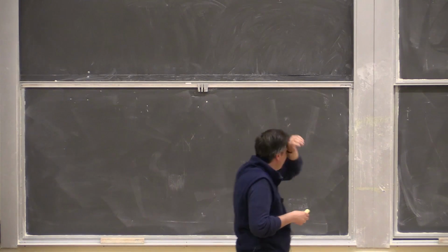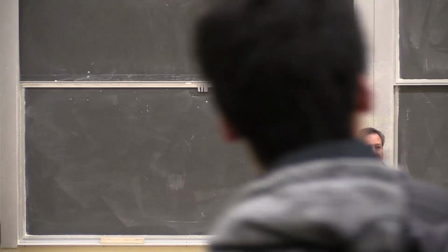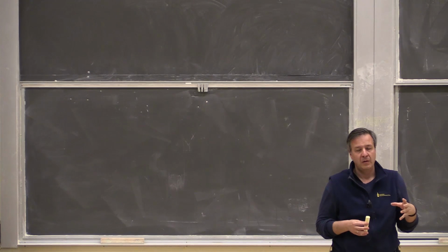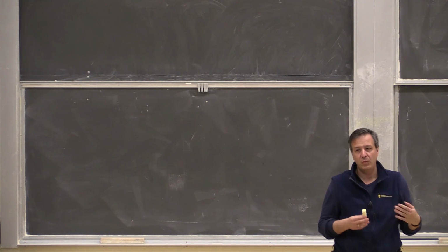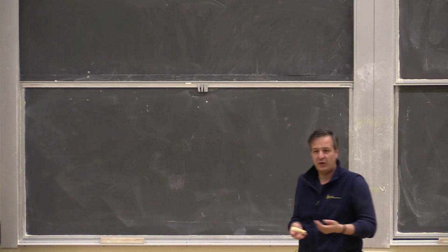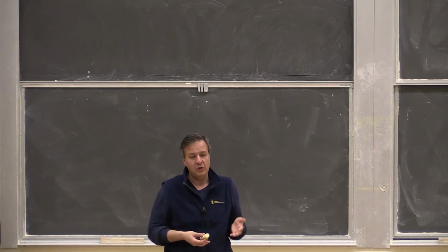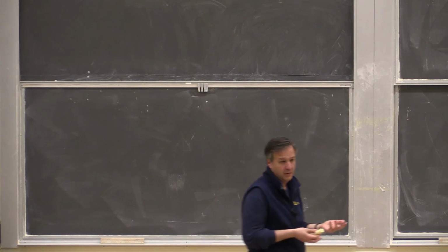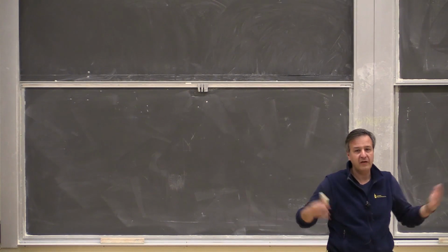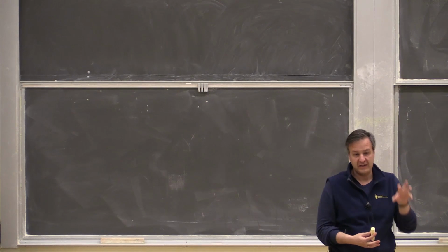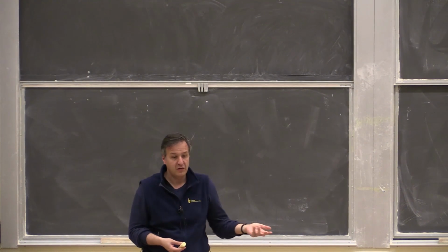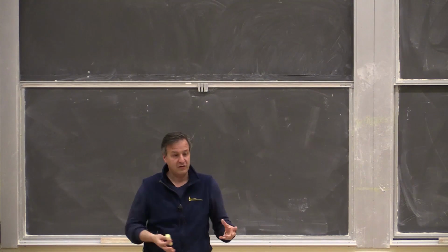So it's good. Okay, so today we're going to do some more advanced op-amp based circuit architectures, but also show you that pretty quickly when you're doing op-amp circuits, you won't even be doing nodal or KVL, KCL, but be able actually to solve these circuits by inspection. Right? And they will get bigger and bigger, but you'll be able to recognize the blocks, just like we did with resistive dividers, voltage dividers, current dividers, parallel series resistors.